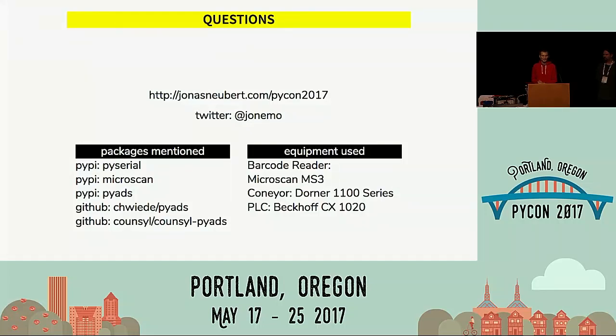Well, many questions in there. The answer is no. So basically, for every device and for every application, you really have to judge what's the right thing to do. In some cases, it is cut the cable, send the voltages that it wants, and you're good. Sometimes there is a pretty good, let's say, Windows software, and the vendor even gives you a COM object or a DLL or ActiveX object, something like that, and maybe then you just want to wrap that. It really depends. It also obviously depends on encryption and things like that. Some vendors encrypt the communication. So long story short, it really depends on a specific device. I always, and you kind of heard that during this presentation, try to shoot for pure Python and sending bits and bytes over Ethernet or serial ports.